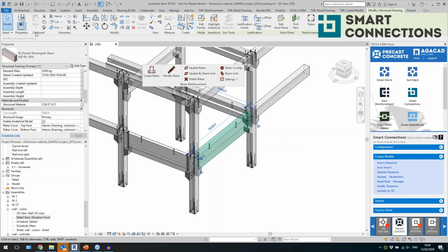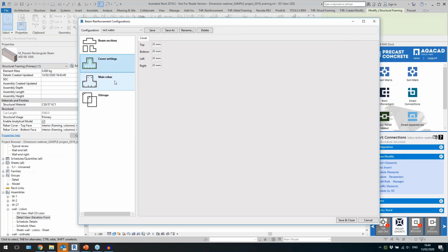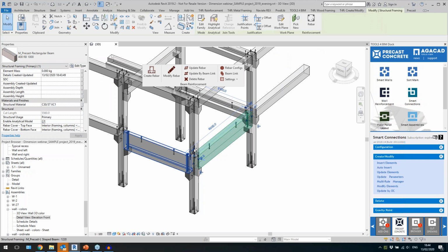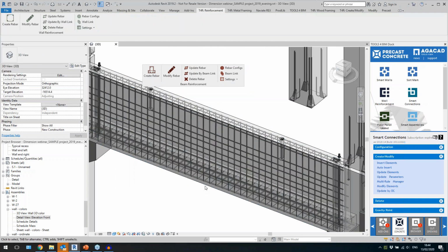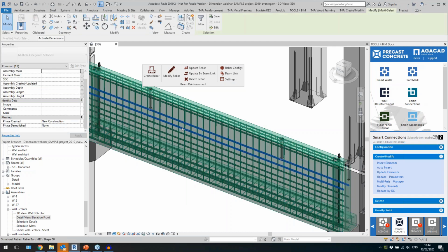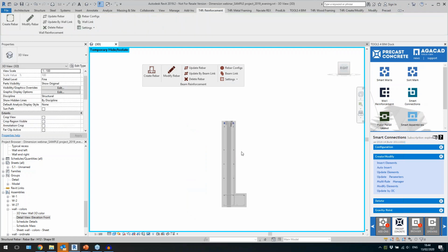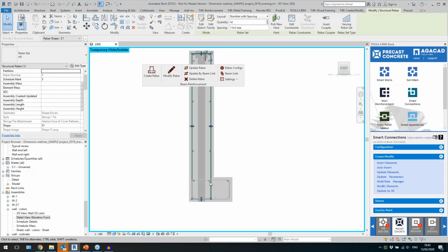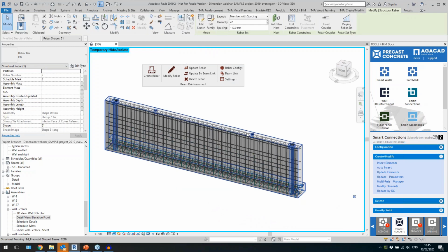I have here a configuration to place reinforcement for the beams, right? I have different kinds of settings here, and then what I want to show you, let's try to do that. I'm just gonna pick these and then click on create reinforcement. Oh, it worked out, so it's good. So what I have here, maybe I can just isolate a couple of elements. I'm just gonna show, let's say, so I have reinforcement created, right? This one's this stirrup. I have some layout in that direction.